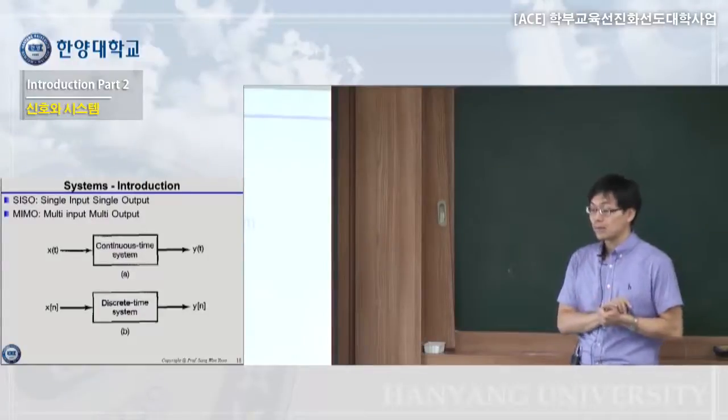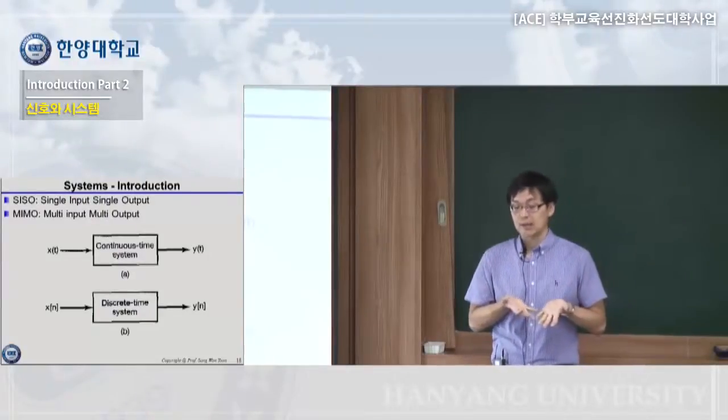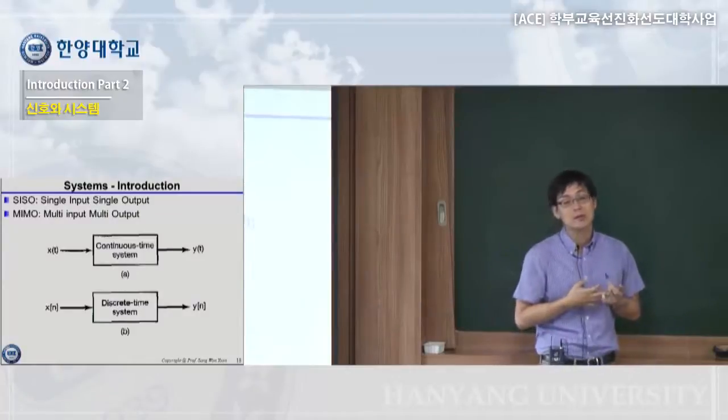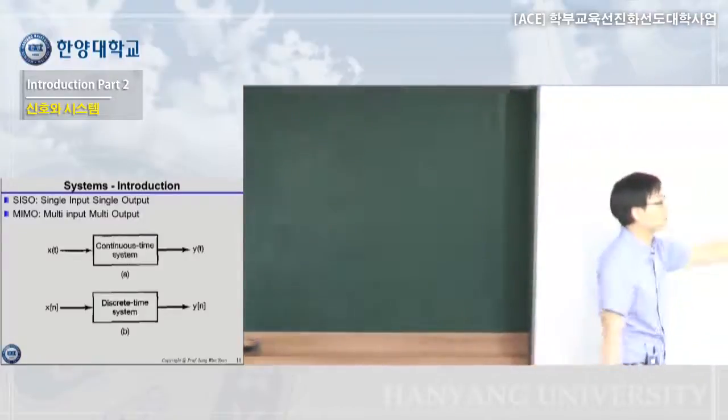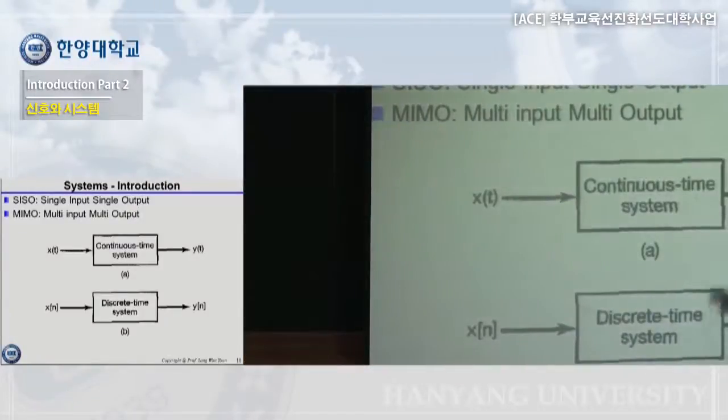So system we can define likewise in many ways. There is the continuous time system. Input is a continuous signal, output is a continuous signal, and as input and output are continuous signals x(t) and y(t), the system will be a continuous system. If input is discrete and output is discrete, then we have a discrete time system. So both of them look like a box, but they are actually different systems. Sometimes we'll cover it briefly in a sampling section in a later chapter.